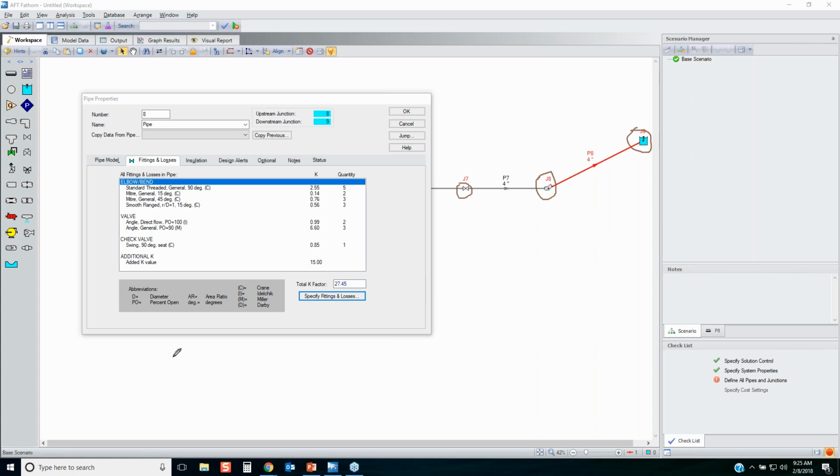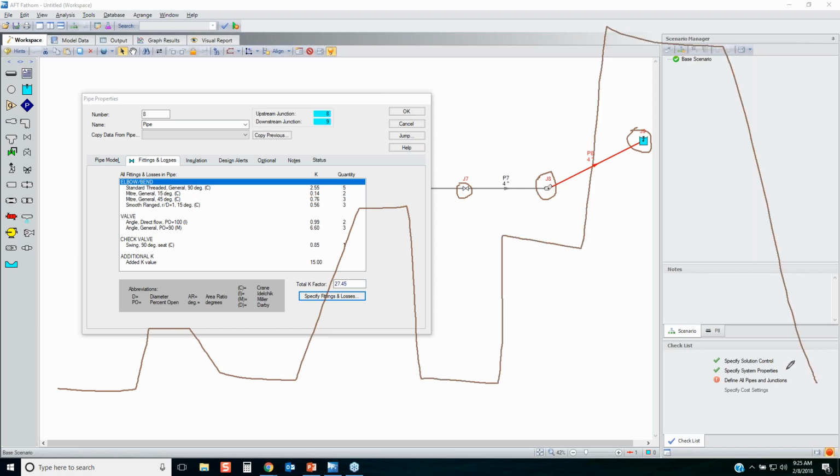That being said, if you have a really long pipe that's doing something like this, it's traveling all over the place, well, you could model this in reality by putting branch junctions all throughout this area. This is the branch junction right here, and that's simply a connector point for pipes. And so you can put a branch junction at each of those locations simply to get the elevation change of your model. However, it's going to be gruesome and take a long time to do. And again, you've got all these extra short pipes, and you don't want to deal with doing that.